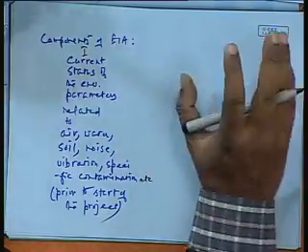I mean, the project has not been started, but you can have a general assessment. Say, what is the quality of water, what is the TSS, TDS, then dissolved oxygen, or particular amounts of, say, sulfate, bicarbonate, the ferric ion. All this can be estimated for water. Similarly, for air you can find out the concentration of oxygen, nitrogen, sulfur dioxide, carbon dioxide, carbon monoxide, all these things prior to the startup of the project.